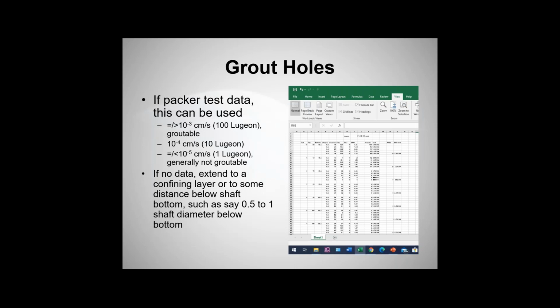So back to grout holes. We're still looking at the number, the orientation, those things. Now we're looking at how deep to take those holes. And Adam did a great job of going over the importance of hydraulic conductivity testing. It is for consolidation grouting. It's the number one piece of information that I think is important for that type of work. So we need to look at that data.